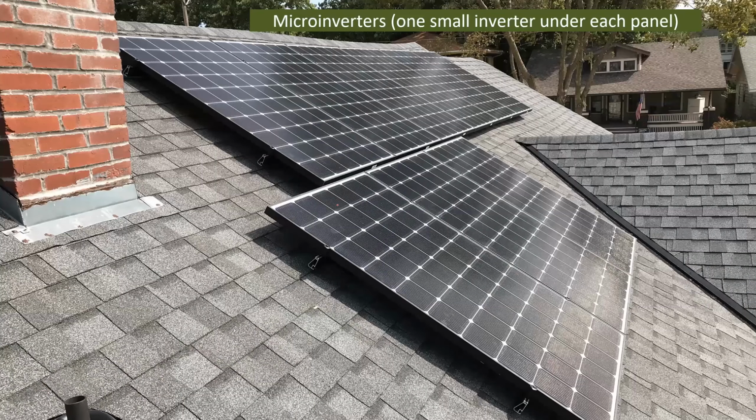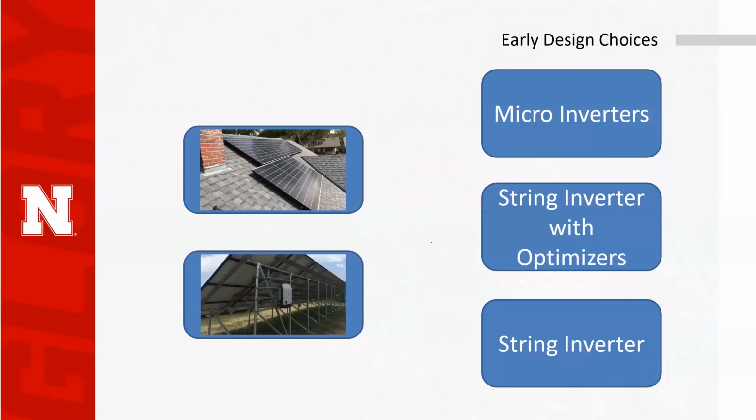If you have a roof mount, you are probably going to be thinking about microinverters, which are one single small inverter that lives under each solar panel. And it's turning that DC electricity from the solar panel into AC right at the solar panel level. So there's one under each one. And then those are connected together, and then they go into the roof, underground under this solar panel here, and get connected to the system. Microinverters are the most expensive, but they tend to be really good. They're easy to install, and they tend to be really good for roof-mounted applications.